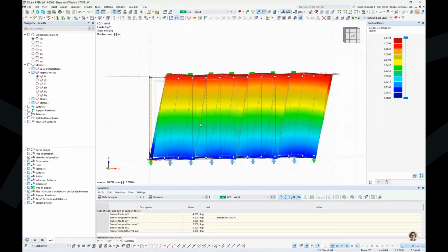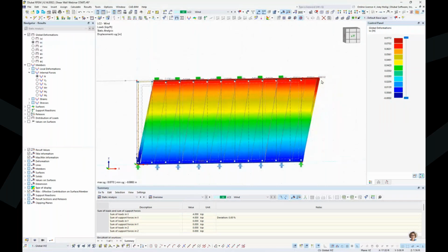So based on this applied wind load, maybe we want to look at deformations only in the X direction, and we see a total value here of 0.0772 inches. So not very high, but this entire system is working together. Just like what we talked about with the deformations from the PowerPoint and the SDPWS, those 4 different points. We have the nonlinearities for the line hinges. We have the sheathing, the different panel widths. Again, everything acting together to determine these deformations that we see here.